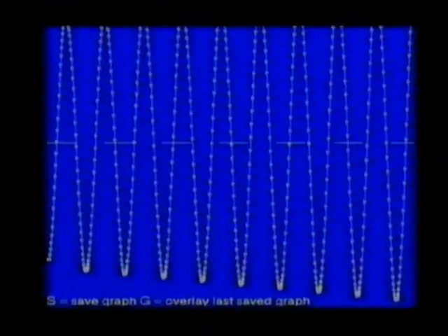Let's increase the integral term. I'm obviously trying to simulate integral wind up here, and there we've got it. The I term has got so large with respect to the proportional term, the system has gone unstable, and instead of an exponential decay, we've got exponential increase. So let's go back to something that was stable. 40, 10, 5 pixel delay. There is a proportional term, proportional and integral.